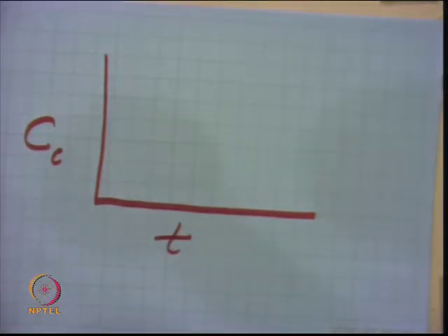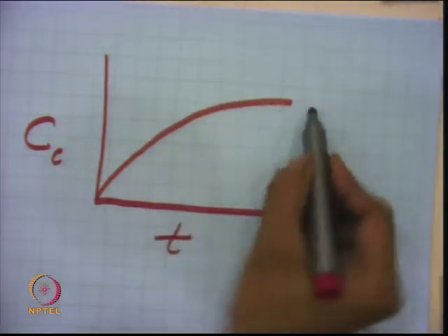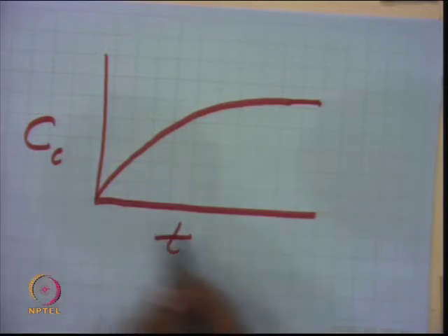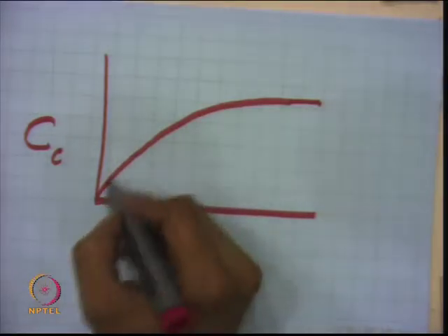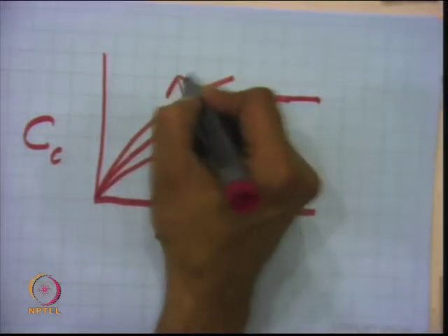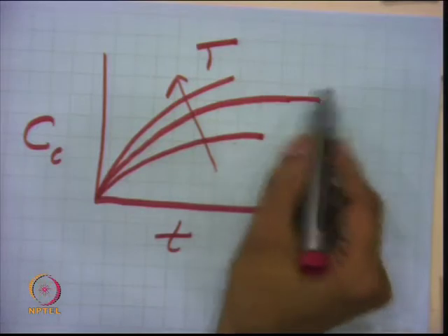This will be a function of temperature also, because the higher the temperature, the more the severity of the reaction. Generally it is known as the asymptotic coking rate. This will be a kind of profile related as a function of temperature, and one can very easily calculate it at different temperatures. Increasing the temperature, the coke on the catalyst will increase, and this is known as asymptotic coke rate formation.